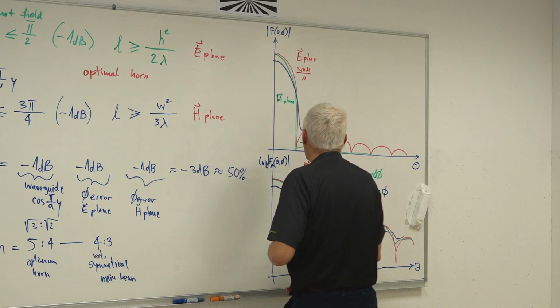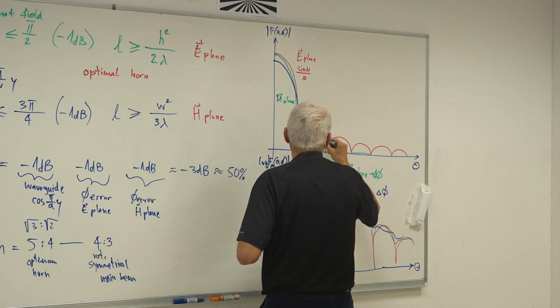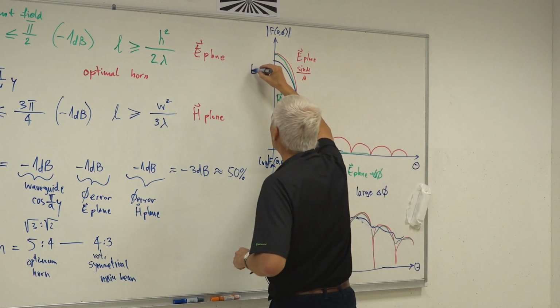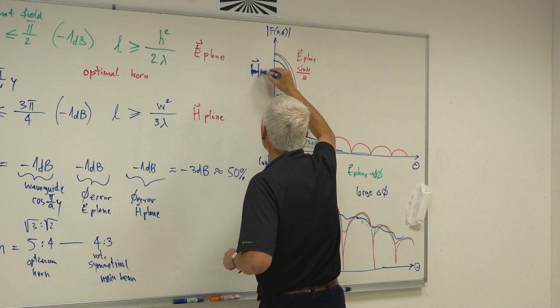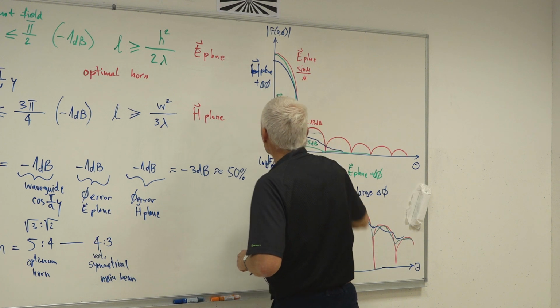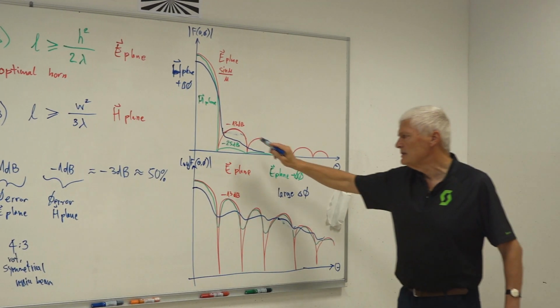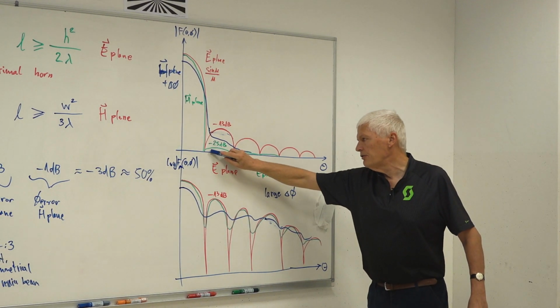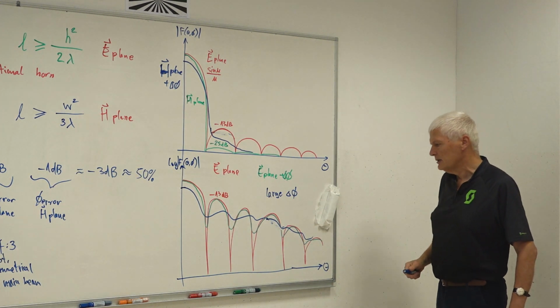Practically all minima and maxima here disappear. This thing simply goes down, in some way like this. So this is the H-plane, plus phase error, plus delta-phi. In the H-plane, I seldom see any side lobes in the practical measurements because of this. This is only for the theoretical distribution, illumination with no phase error at all.